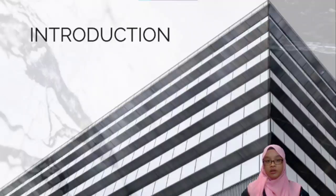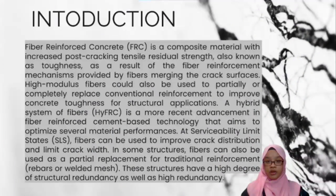Here I will present about introduction of fiber reinforced concrete. Fiber reinforced concrete is a composite material with increased post-cracking tensile residual strength, also known as toughness, as a result of the fiber reinforcing mechanism provided by fibers bridging the cracked surface.